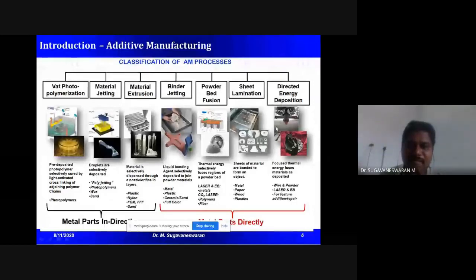The nozzle is very unique. It is a coaxial nozzle, as we are using in the cladding process. So this coaxial nozzle will have a laser, and to the circumference of the laser, there are multiple channels. These channels will feed a powder. So that is the construction, internal and external construction.